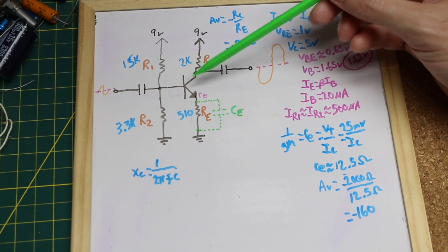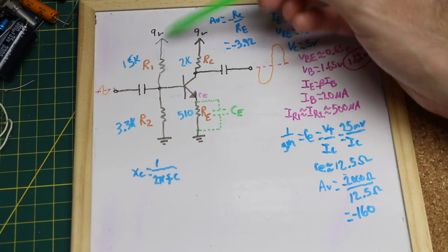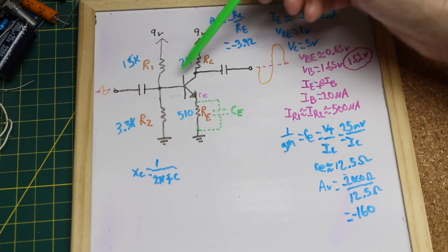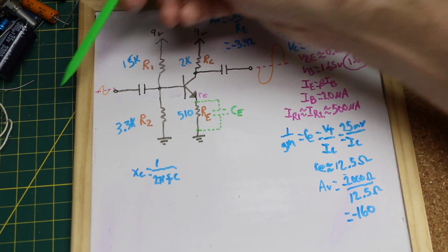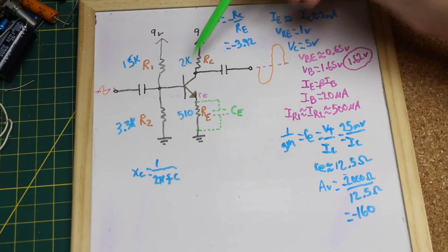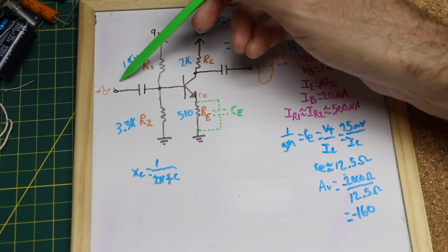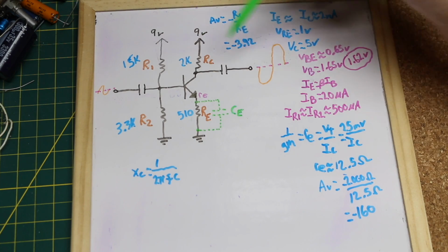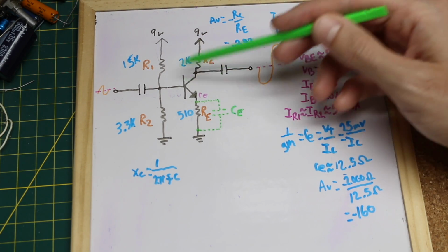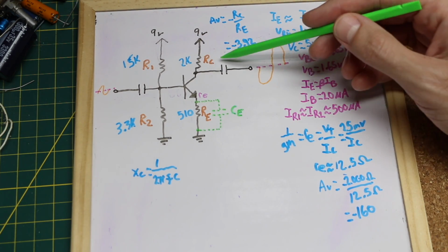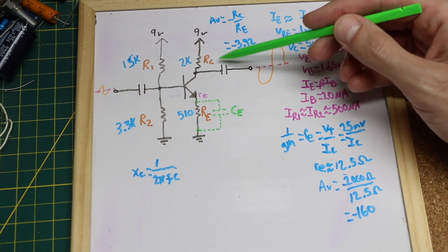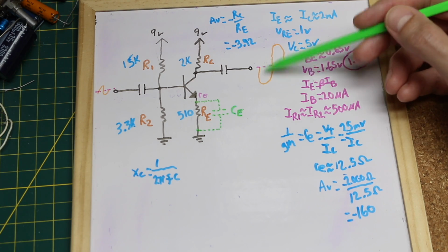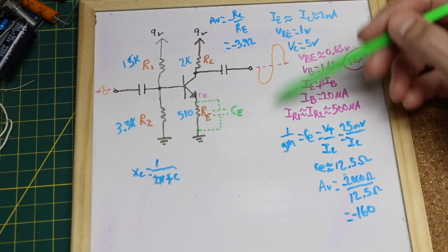And because we don't want our established DC voltages to make their way to another circuit stage, or for any other circuit stages to interfere with our DC voltages, we have a series DC block AC coupling capacitor with our input and output. So to figure out a good value for those, again with the output, I would plan to hook this up to some other input stage with a very high impedance. Let's say it's 1 meg to ground impedance.